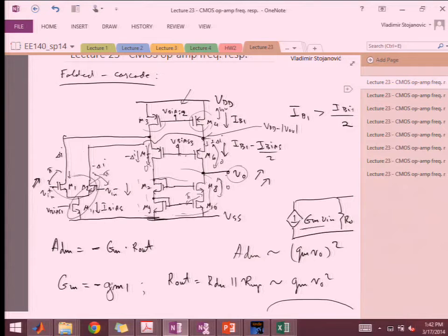Okay, N plus VSS, right? Okay, so how did you figure that out? You go up 2 VGSs from M2 and M9, and then you subtract the VTH going up from gate to drain.